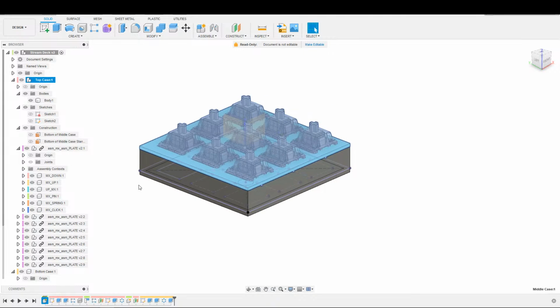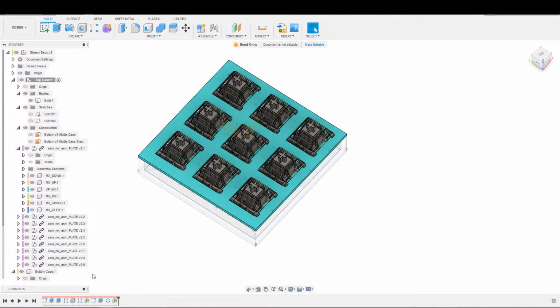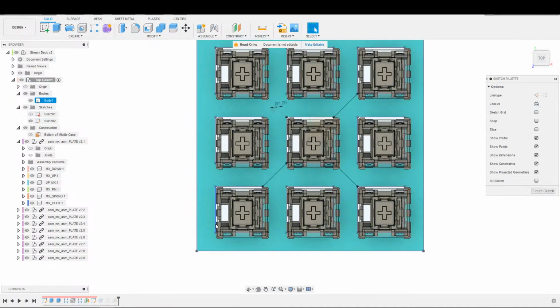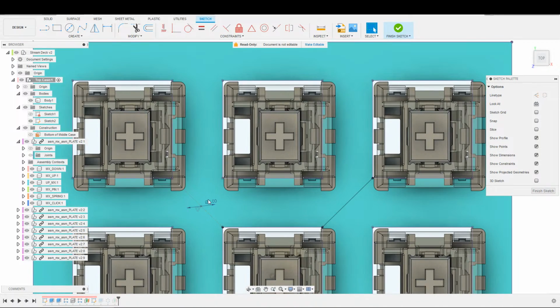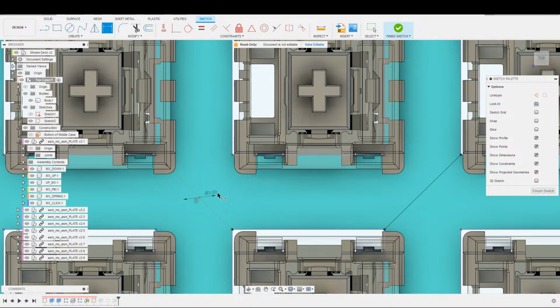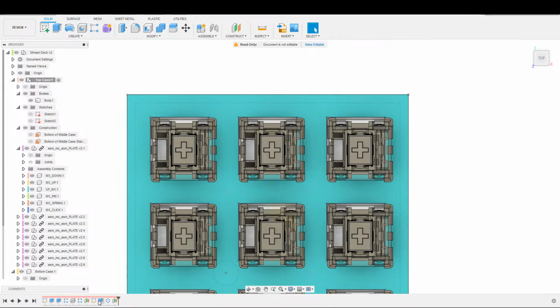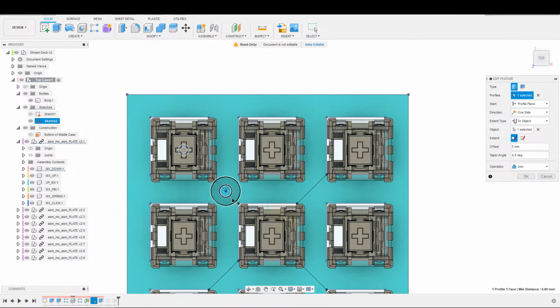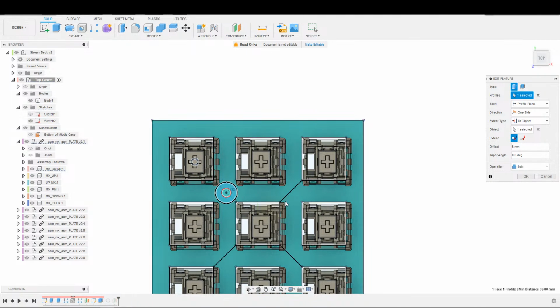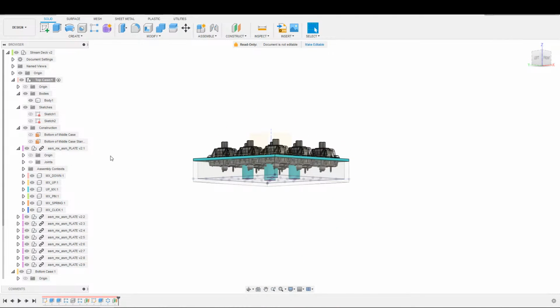So this is now going to be top case. Top case. I'm going to come into the top case, grab my circles again, and this is going back to a 3mm M3 bolt with a 2mm ring around it. 2mm. Finish. And then you are actually going to extrude like this. Okay. So you're going to extrude like that. We do not need the ring on the bottom anymore.